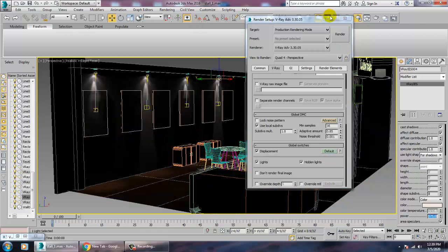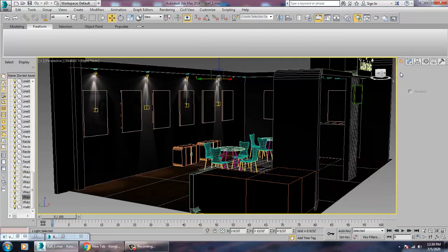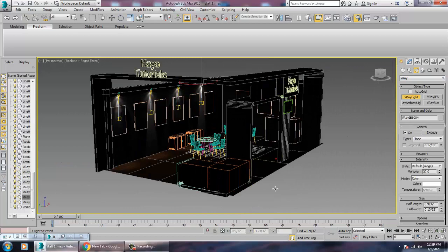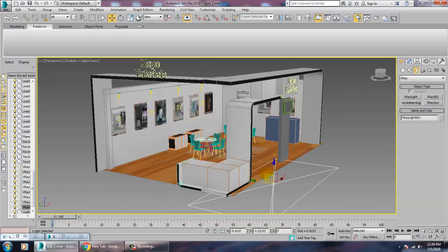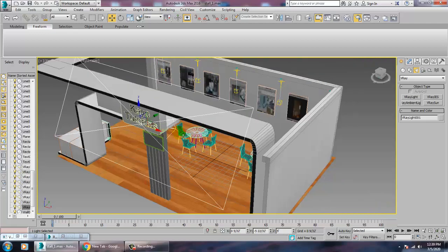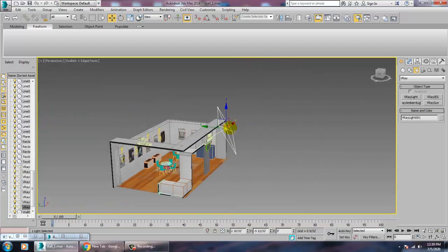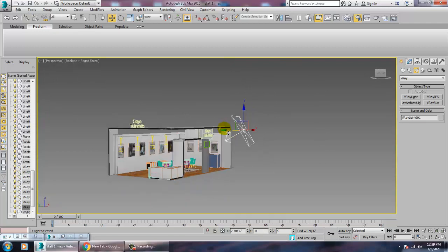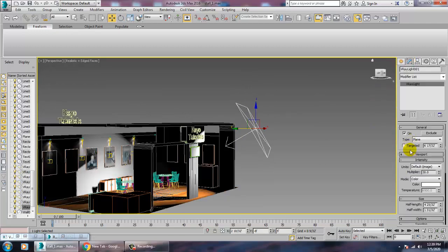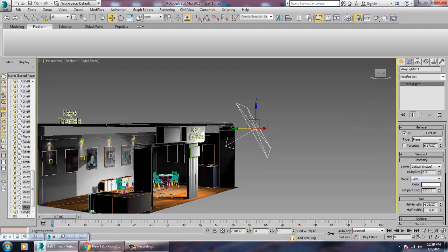and we'll take one more V-ray light right from here, illuminating the scene over here right from this direction. So rotate the light, push this over here, select this light and reduce the multiplier to 0.5.